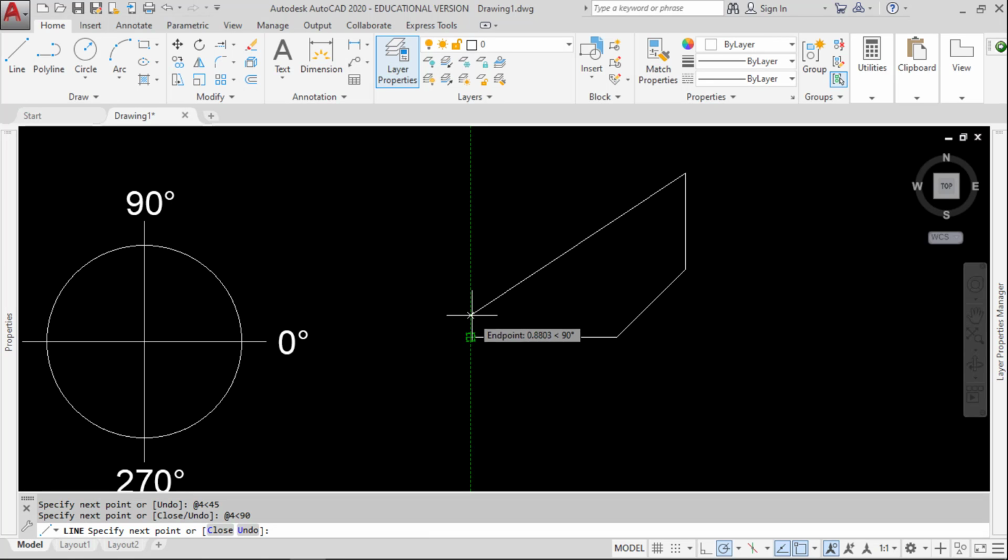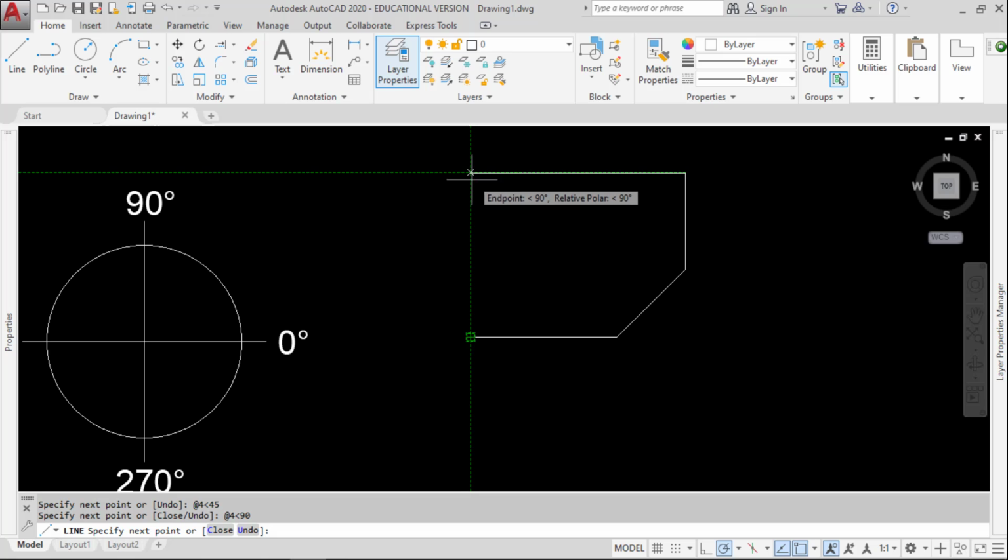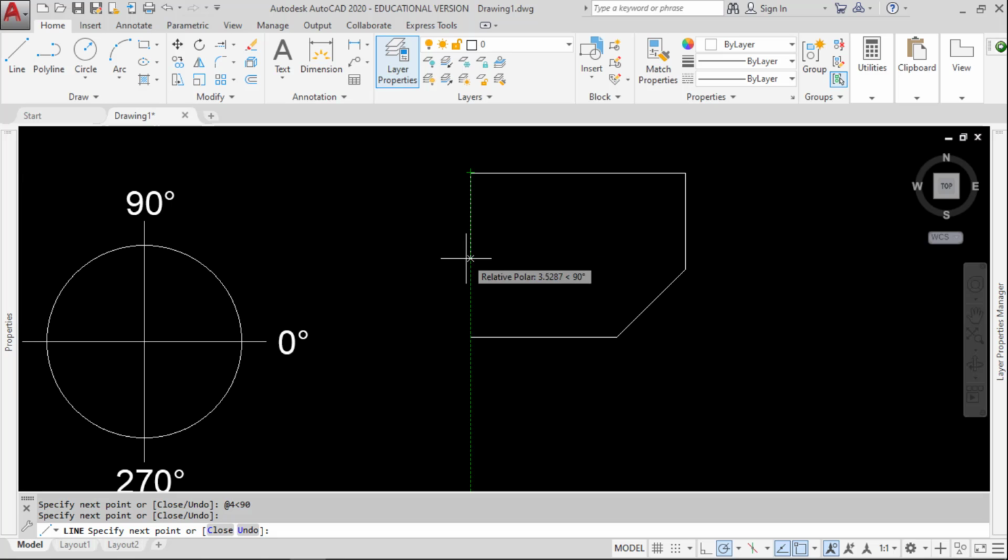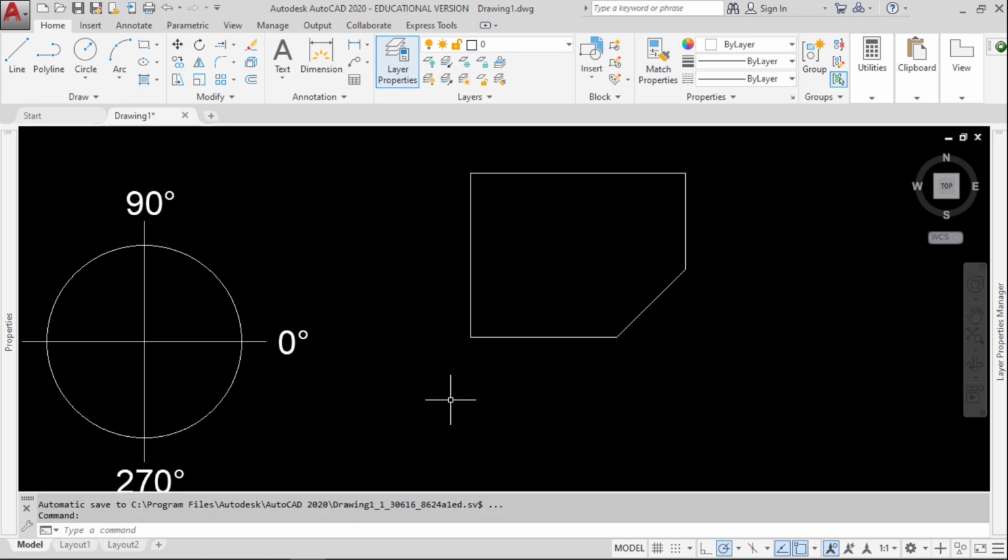So I'm going to hover that point, let it sit for a second or two, and now I'm going to move my mouse relatively straight up. And see, I get that green vertical line. That tells me that I am snapped in to the end point. Now it's going to click to horizontal. So I have a vertical green hidden line and a horizontal green hidden line. And that tells me that when I complete this, those 2 points are indeed vertical from each other.